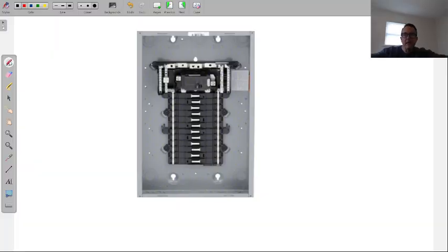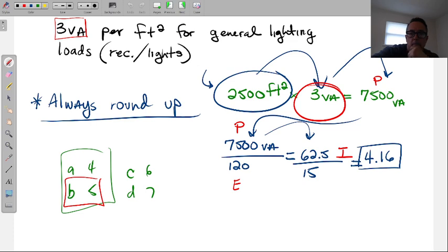So you limit the amount of outlets that you put on a breaker. You set a number. That's why we have that rule of 12, because we've determined 6 outlets on a 120 volt, 15 amp breaker in a house. That's good enough. That's not going to lead to problems. All right, those are good questions, because we want to know how many outlets we can put on a breaker. So about 6, and keep that rule of 12 and it'll work out good. Going back here.